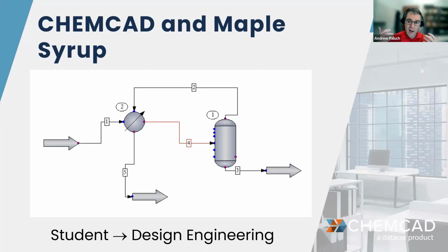And then not only how could you make it more efficient from a conceptual discussion, but they could actually go into CHEMCAD and implement these and directly see the effect, right? They can add a membrane, even though they haven't quite studied membranes in their classes. They could implement this strategy of thermal integration, even though we haven't discussed thermal integration yet, which usually comes later on in their senior year.